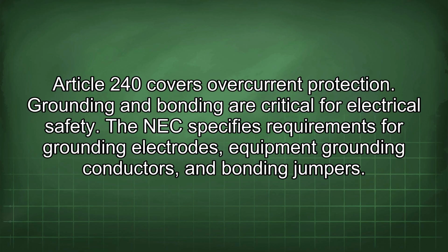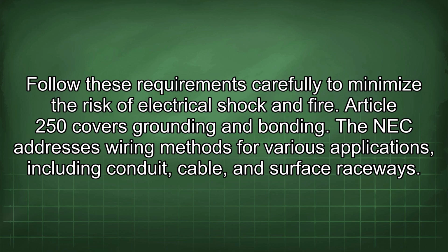Grounding and bonding are critical for electrical safety. The NEC specifies requirements for grounding electrodes, equipment grounding conductors, and bonding jumpers. Follow these requirements carefully to minimize the risk of electrical shock and fire. Article 250 covers grounding and bonding.